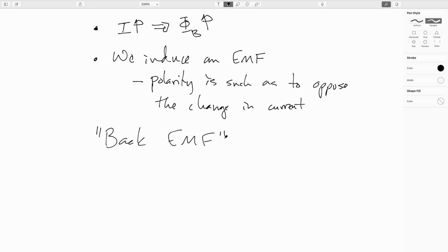So this explains why electric cars can smoke straight off of the stoplight virtually any car that isn't built to be a flat-out racing car in a professional racing series. This is because they produce maximum torque at 0 RPM because there's no back EMF. As the RPMs go up, the EMF increases and the available torque that the motor provides decreases.